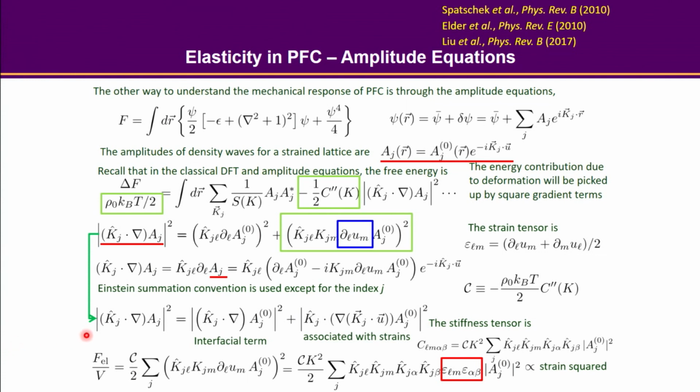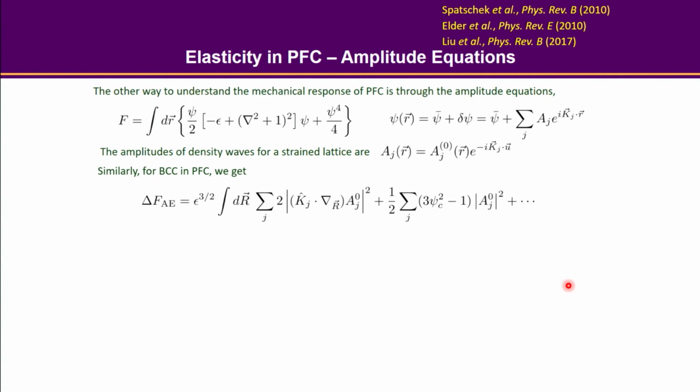So one way to make a connection with this stiffness tensor is that the energy equals 1/2 something times strain squared. So whatever is in front should be my elastic moduli, right? So I just said, everything aside from this epsilon squared and 1/2, that will be a C, K squared summation, all these products times A squared, is the stiffness tensor. So just to work that out a little bit.